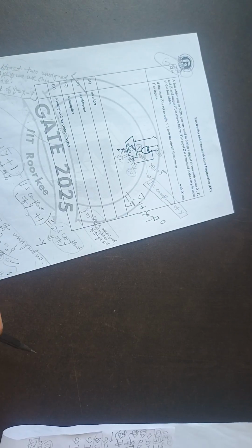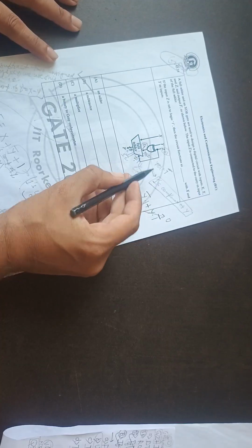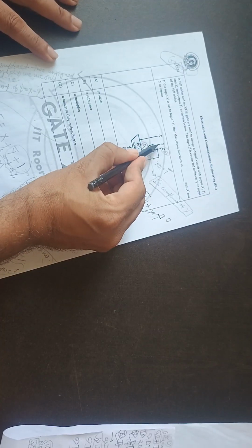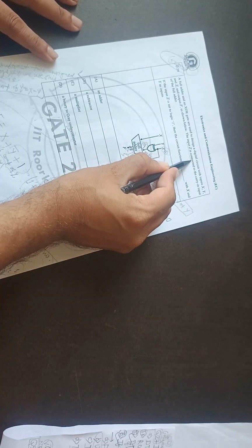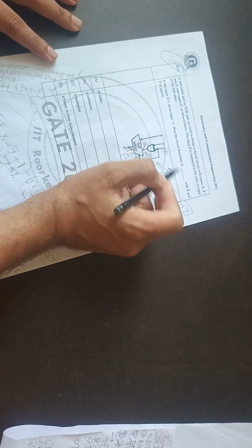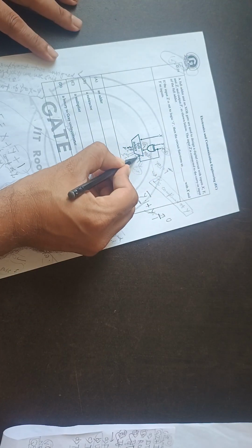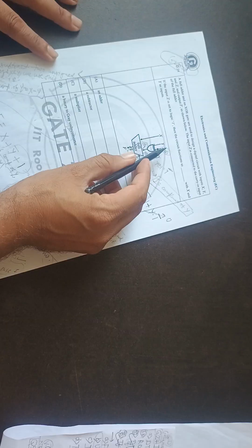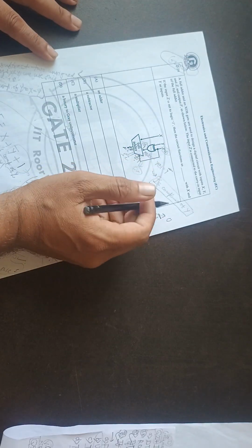Second question is on a full adder circuit, and there is an XOR gate also here. Here it is input X, here it is Y XOR, and Z is always equal to 1. Input Z is connected to the carry in input, and this is 1 also as carry in. So if input Z is logic 1, the circuit will function as?